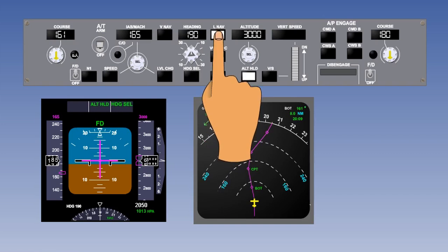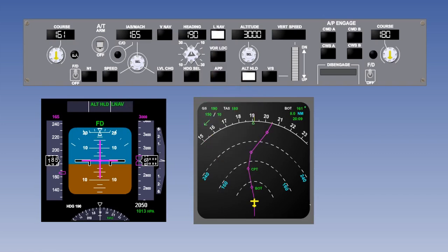The other way to set up lateral navigation is by using LNAV, which utilises the Airways Track database in the flight management system. The flight director computer, using a combination of inertial navigation and global positioning systems, and the selected track from the flight management system, sends commands to the primary flight display, so the pilot can follow the selected track. This system can be used all the way, from pre-departure until arrival at the destination.